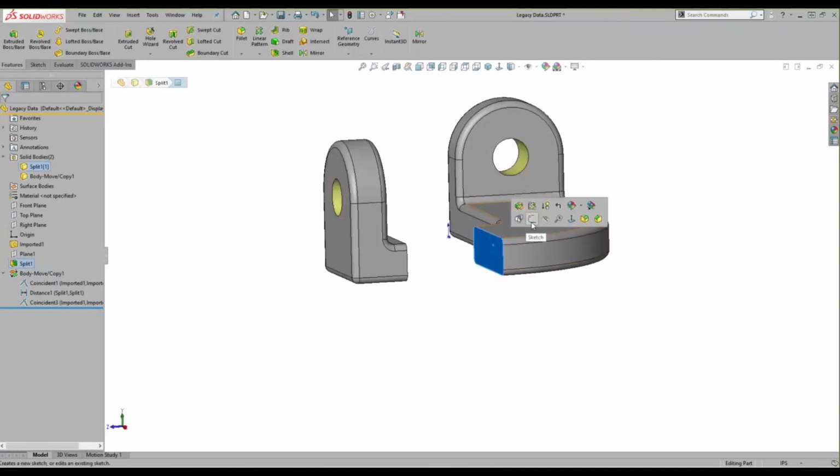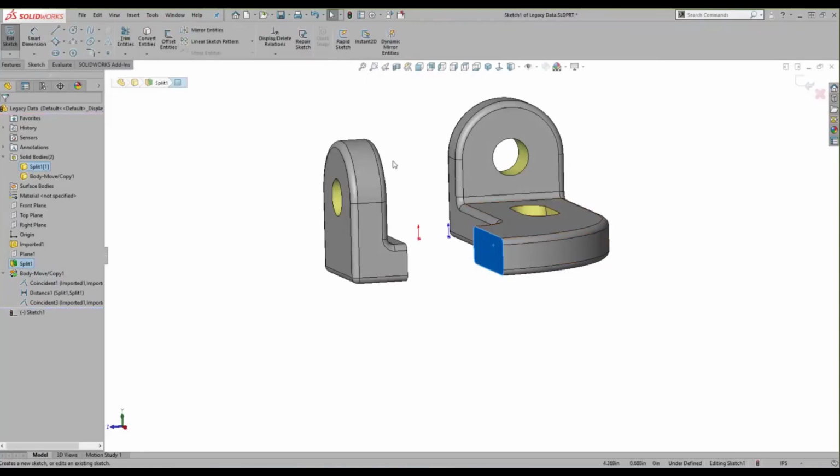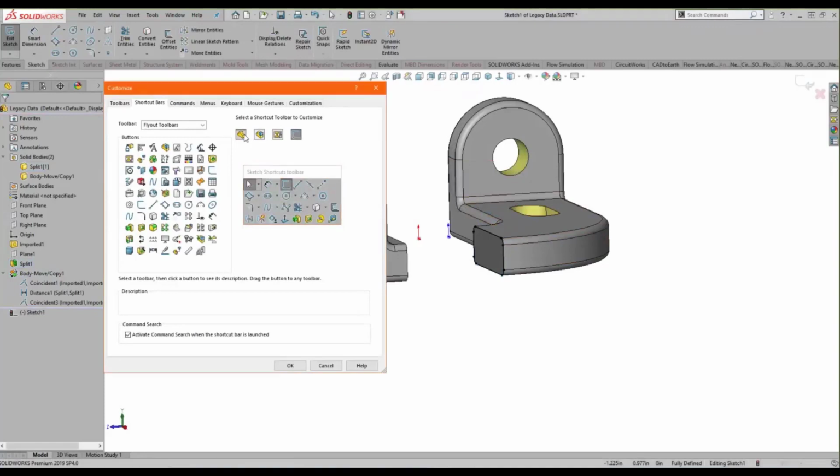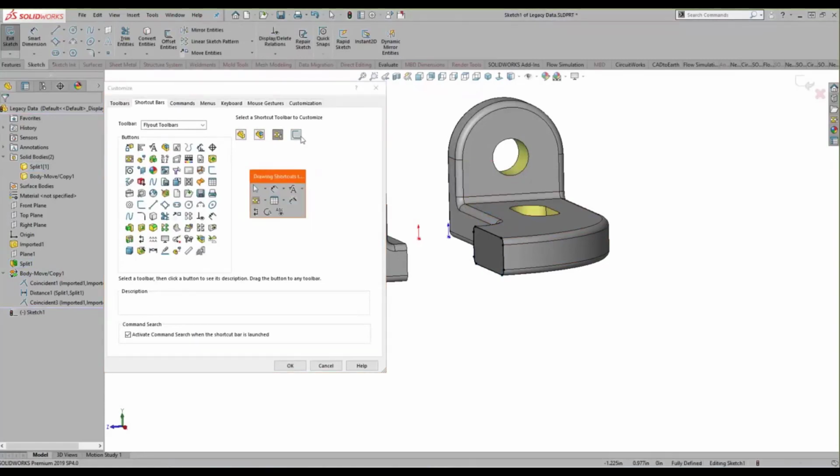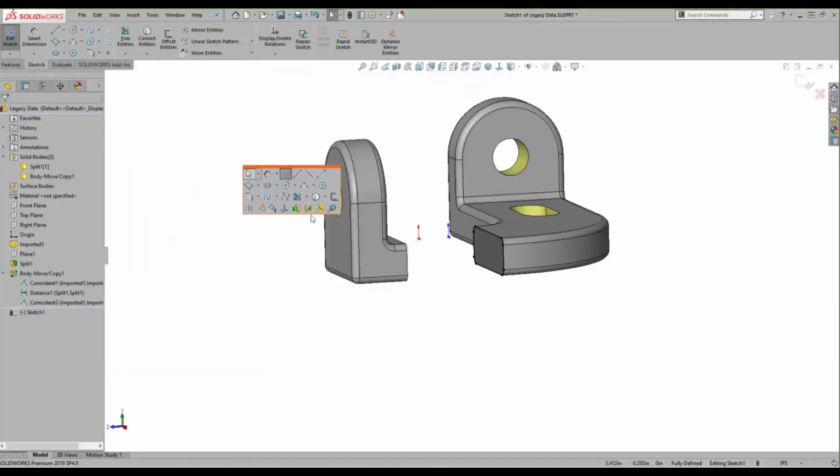And to do that, we'll just select the face, insert that sketch. I'm going to use my shortcut toolbar again to leverage Convert Entities. I'm just hitting the letter S. Great enhancement that they put in SOLIDWORKS, well, a really long time ago. But if you haven't used the S key, the shortcut toolbar, I highly recommend looking into it. I've just right-clicked and chosen Customize. You can set up one for parts, assemblies, drawings, sketches. Yes, I know it's kind of off topic, and this really has nothing to do with multi-body parts, but big fan of the shortcut toolbars inside of SOLIDWORKS.